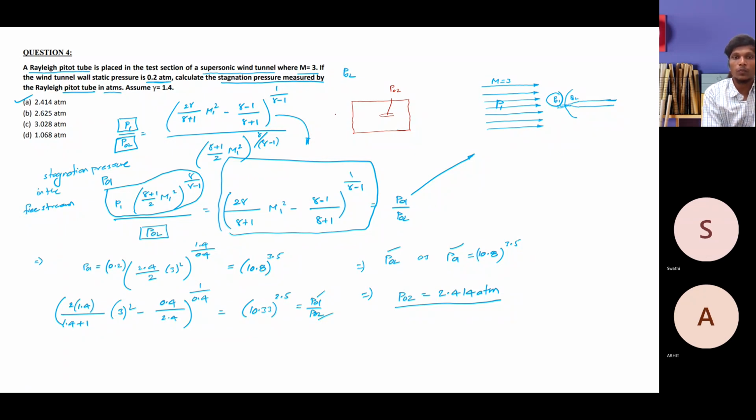Assume that you set all the pressure differences in the wind tunnel, stagnation chamber, and static chamber sufficient to generate some particular value, but we are still checking using the pitot tube. So this pitot tube is measuring the value of P02 only, and you have a static pressure port here that is measuring P1, the static pressure value.